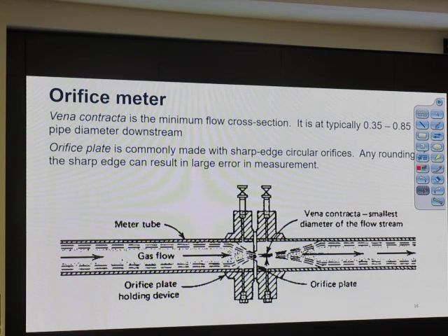Most of the time, when we put this over there, the downstream is disconnected from the upstream. So it doesn't really depend much on the upstream. But if it flows really slow, yes, it changes. But in a certain range, it won't change. So this means this flow meter is accurate for a certain range, not from 0 to something. Maybe like 10 to 90% of the reading scale, that is okay.